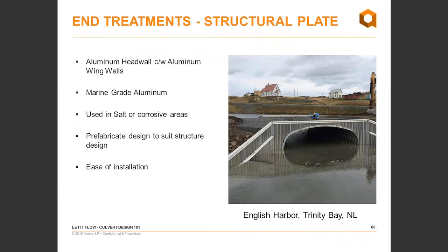Therefore, no concrete footings were required. Had aluminum head walls and wing walls. It's all marine grade aluminum. The head walls come custom fit to the shape of your structure. Installation went really easy. No wait times for concrete to cure. As you complete the structure, you can start your backfilling right away.